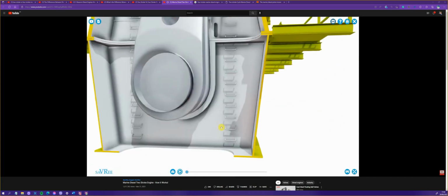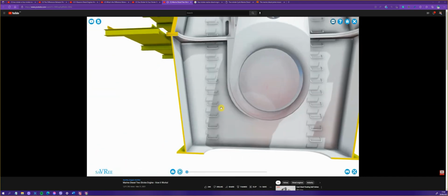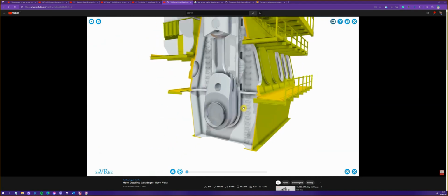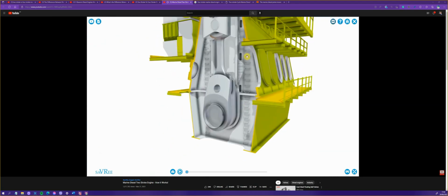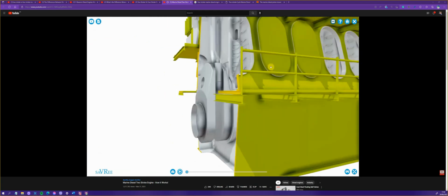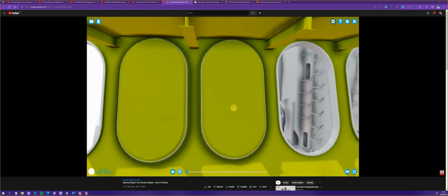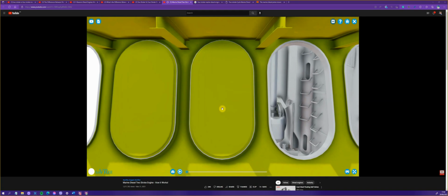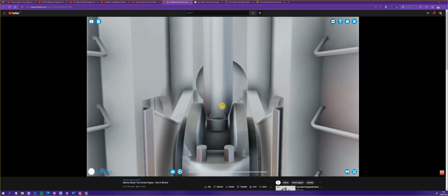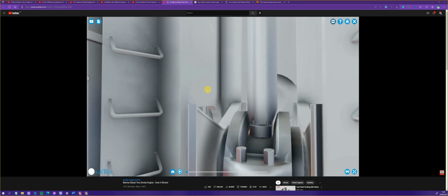These are the rungs of a ladder, and here's another one. These get very slippery. You can climb into the crankcase and use these rungs to have a look around inside the crankcase. What's actually going to happen is you enter through the crankcase doors. I'm just going to go through this one here. And then you can climb around and inspect the area.